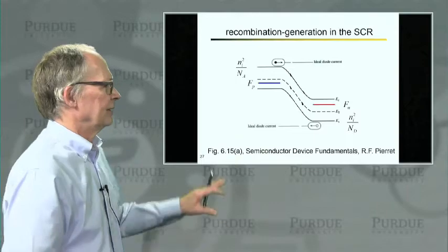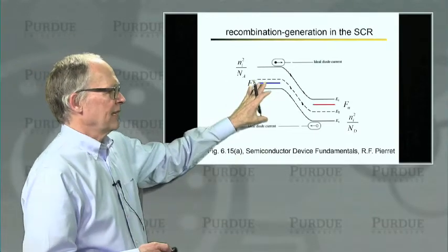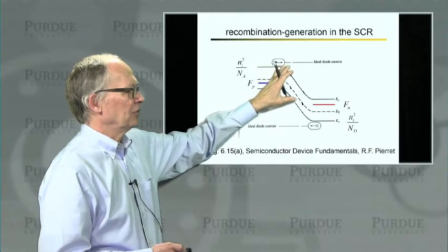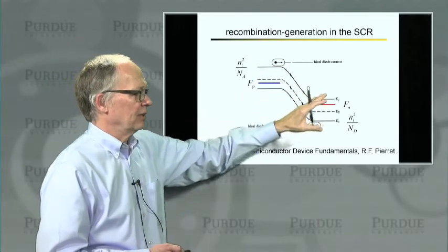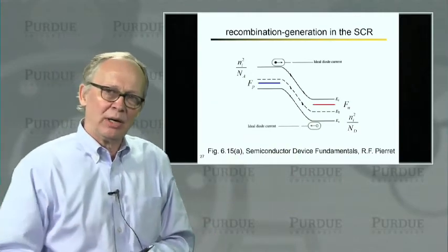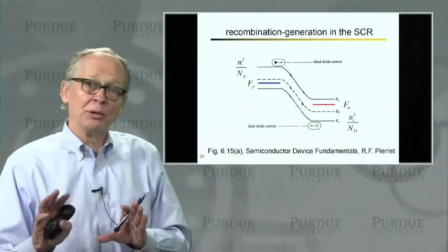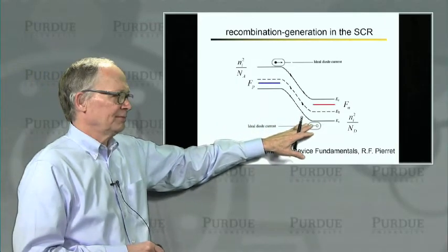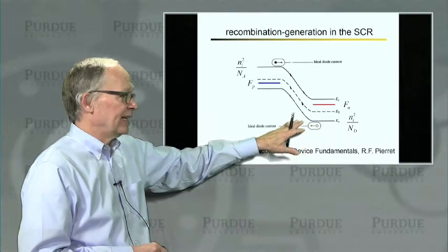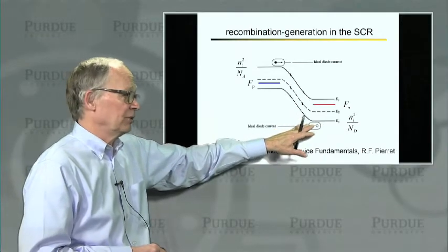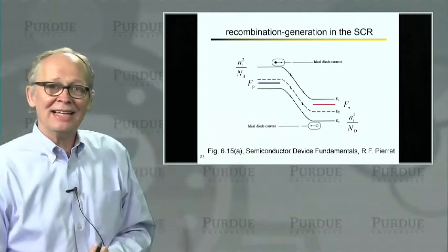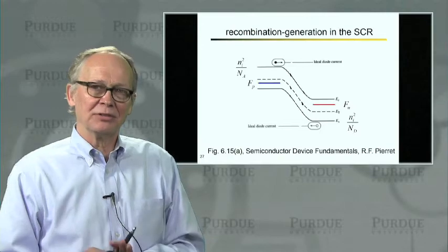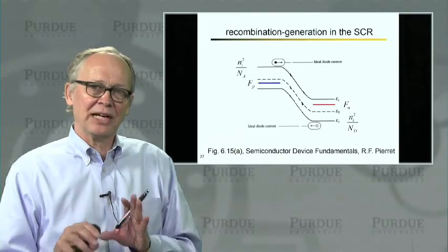So this is how to think about it. This is our ideal diode. In reverse current, we have a few electrons on the p side that, if they get near this transition region, see the high electric field, get swept out, and go out the n contact. That's one piece of my J0. We have a few minority carrier holes on the n side. If they get close to the transition region, they see the electric field and it sweeps them in the opposite direction. They go out the p contact. That's I0 or J0. That's the ideal reverse saturation current.